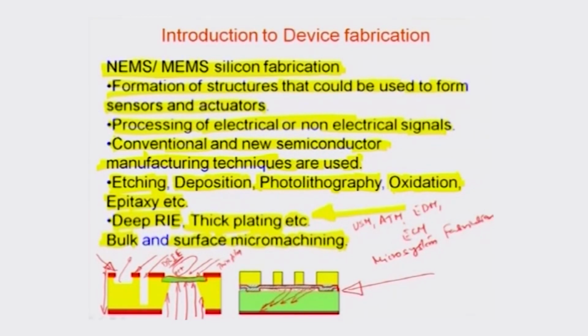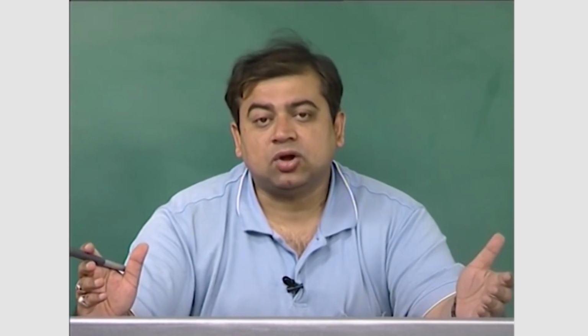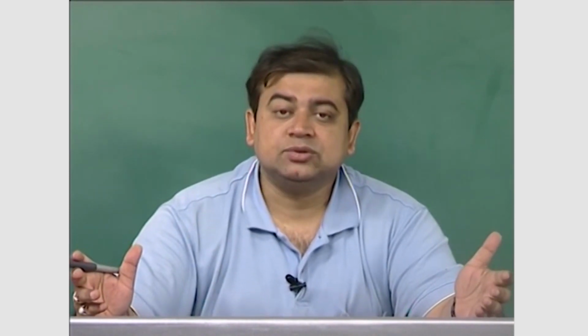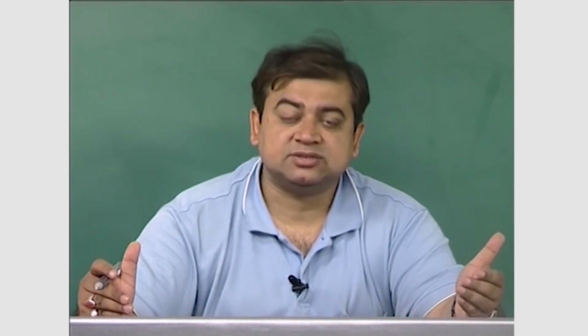Other examples could be deposition of these pillars and posts by using either metals or photoresist, where the structures so realized can be of some significance. For example, all the metallic interconnects in microelectronic circuitry are actually made using such metal imprints. It is called printed electronics. Okay, and it is again an additive micromachining process or a surface micromachining process.